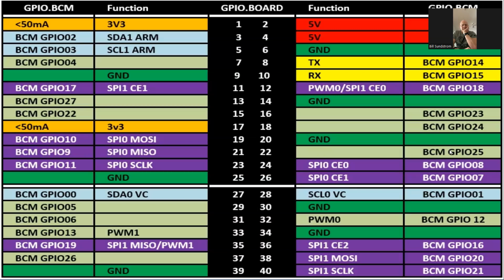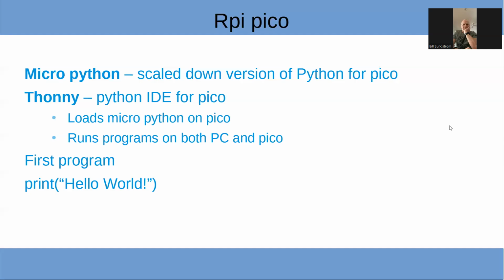In this case, in most of them, you only see like two options for the function. On the BeagleBone, it's as many as 4 or 5. You have this device tree that you have to load to specify what function is mapped to what pin. It's a little easier to do it in the Raspberry.